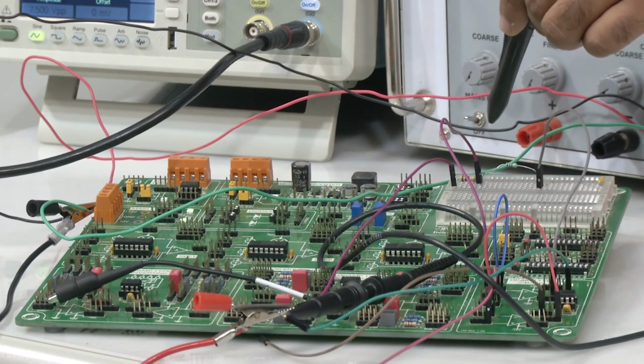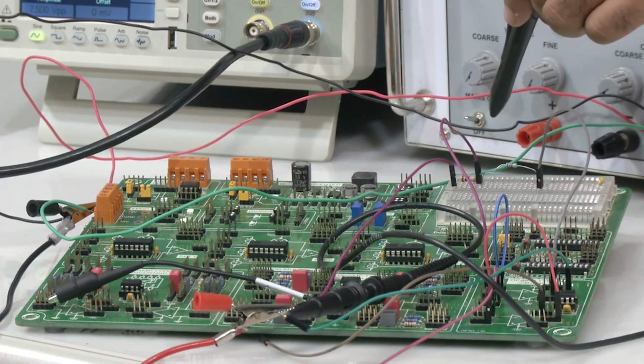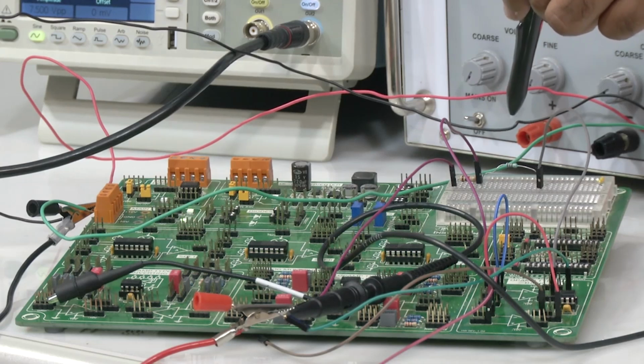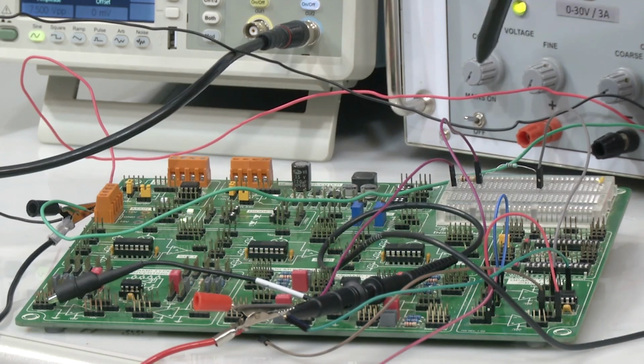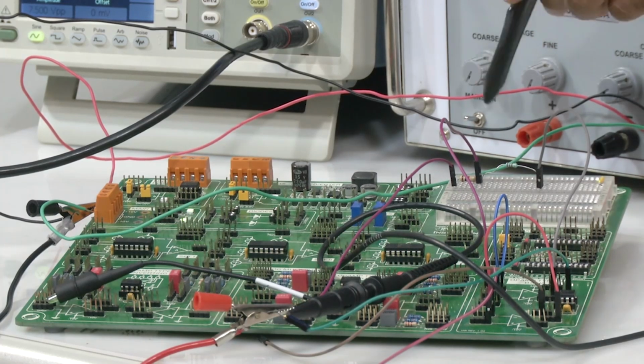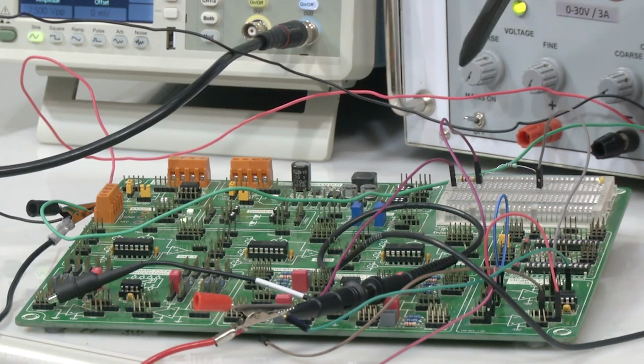What we will do now is keep the input voltage constant at 7.5 volt peak to peak, but change the input frequency and see till what frequency we are getting a faithful output. By faithful output, we mean, say we have made the gain 2.2, correct. For 7.5 volt peak to peak, we should get around 15 to 17 volt peak to peak as the output, which is the faithful output with respect to the gain. So till what frequency are we getting this faithful output, and from what frequency is it going down?